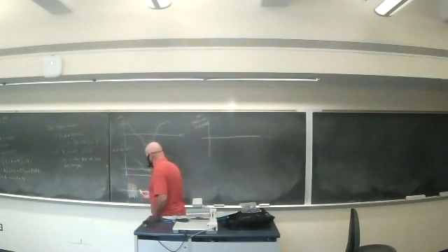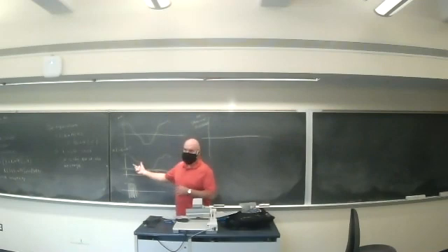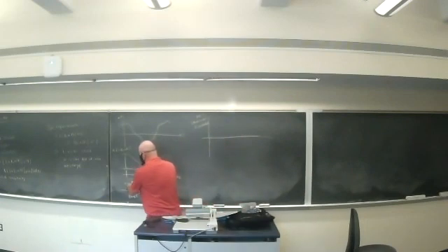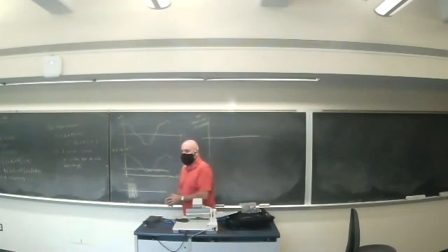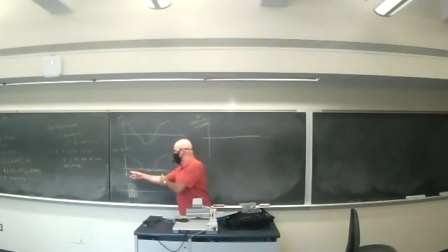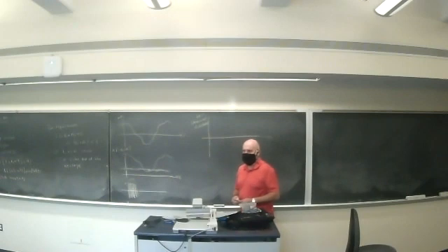On the same time scale, this would appear to be just a solid block unless you really zoomed in, because we're talking about frequencies in the megahertz range, where the message frequencies are a kilohertz, 1,000 times lower in frequency, or 1,000 times the period. So I haven't even drawn these; 1/1000th of a period is compressed even more than I've drawn it.